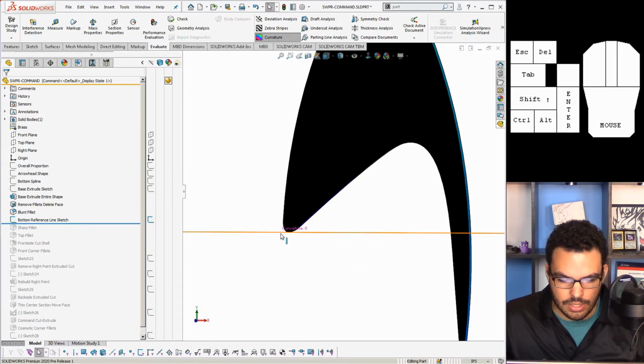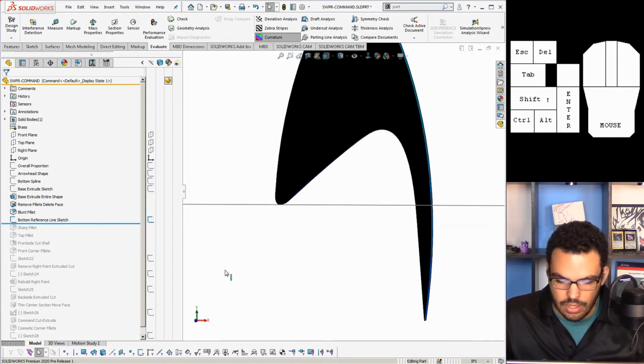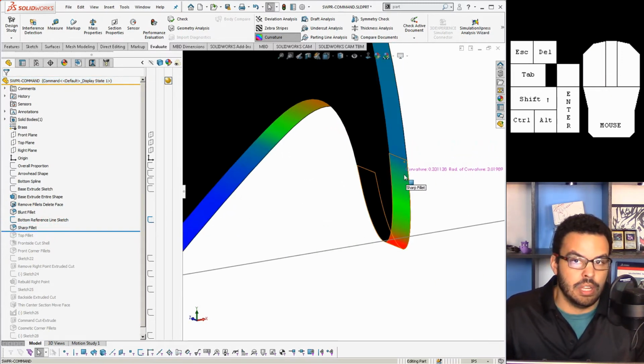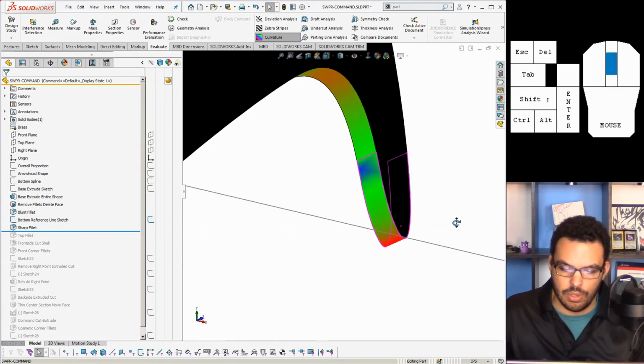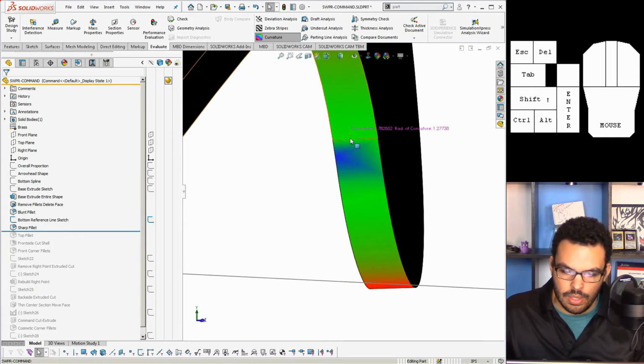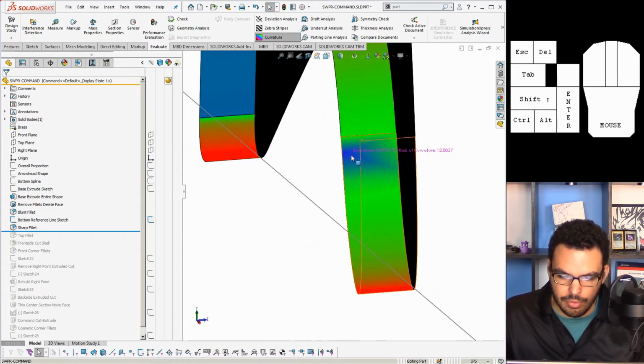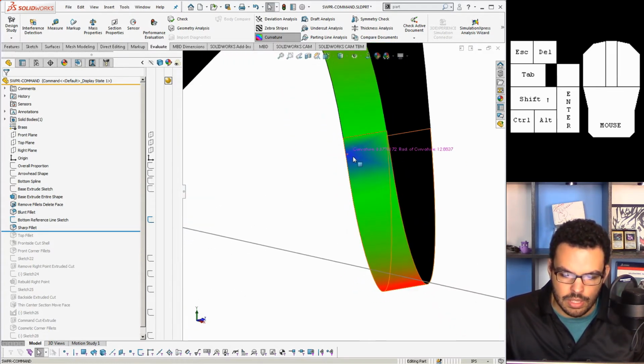Okay, so it looks like he sets a line tangent to this thing as a reference of how to cut this off. Alright, so this thing is sharp fillet. I wonder if he does the same thing. Yeah, I still have my curvature display, so immediately I can tell this was done with curvature continuity. Yeah, it all blends in together really nice and smoothly. Although there's a bit of a flat spot here. That's not too big of a deal.